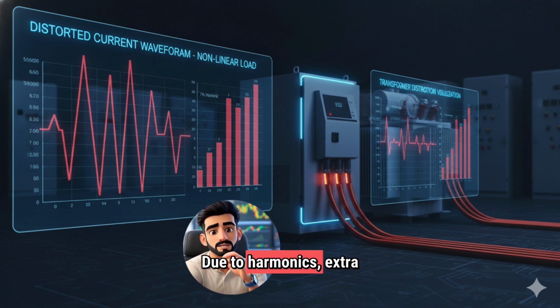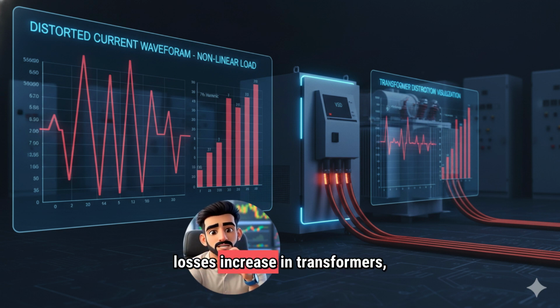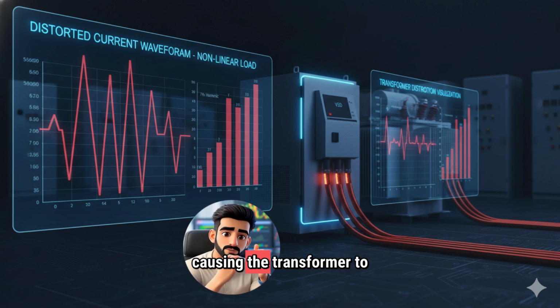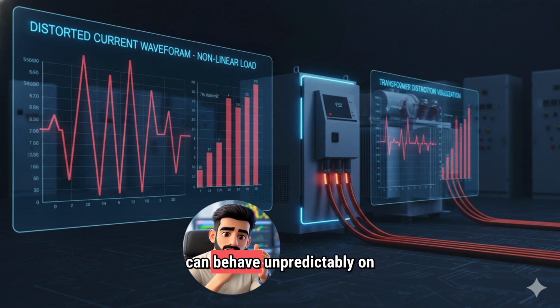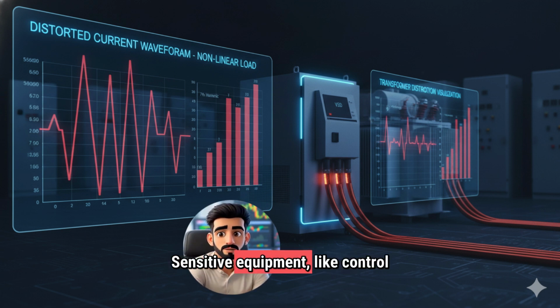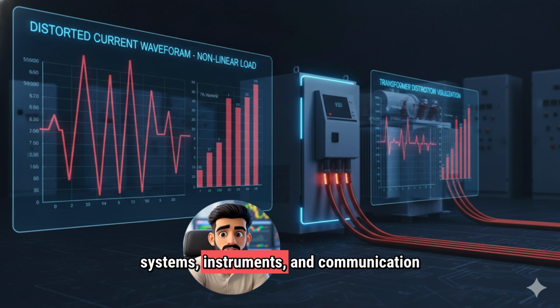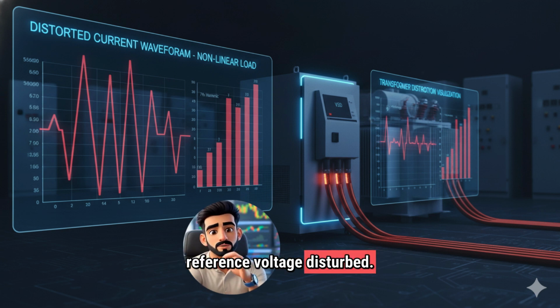Due to harmonics, extra I²R losses occur in cables, meaning more heat is generated. Core losses and copper losses increase in transformers, causing the transformer to heat up. Breakers, contactors, and relays, whose contacts are rated according to sine wave, can behave unpredictably on a distorted wave. Sensitive equipment like control systems, instruments, and communication devices may have their reference voltage disturbed.